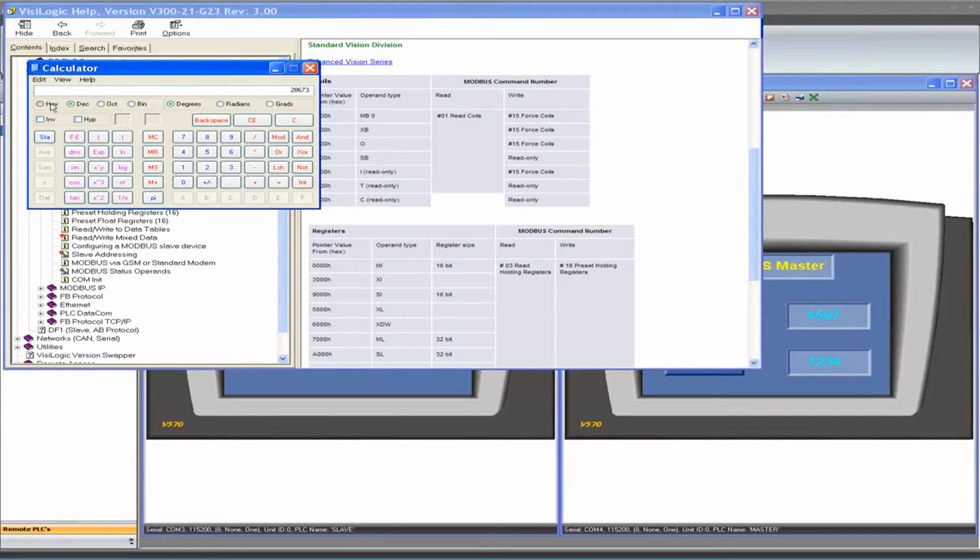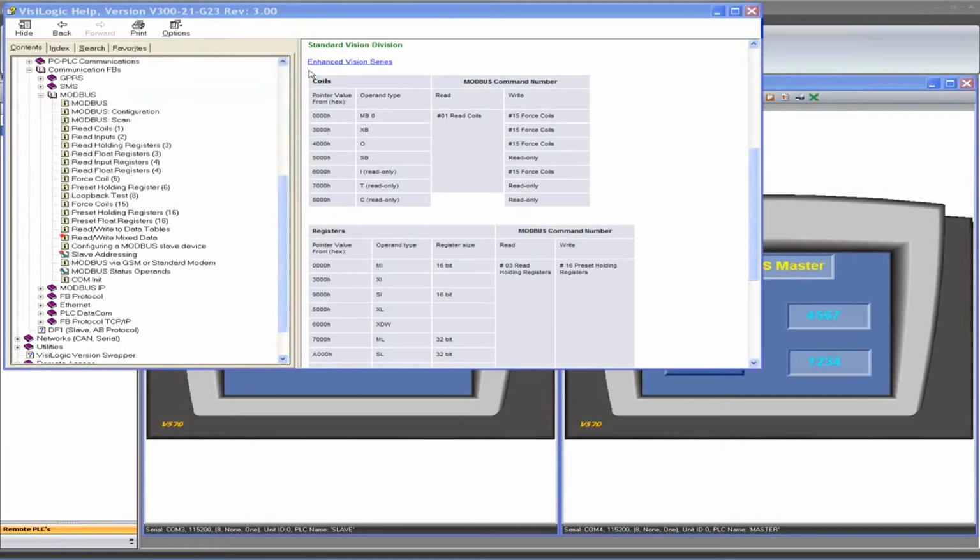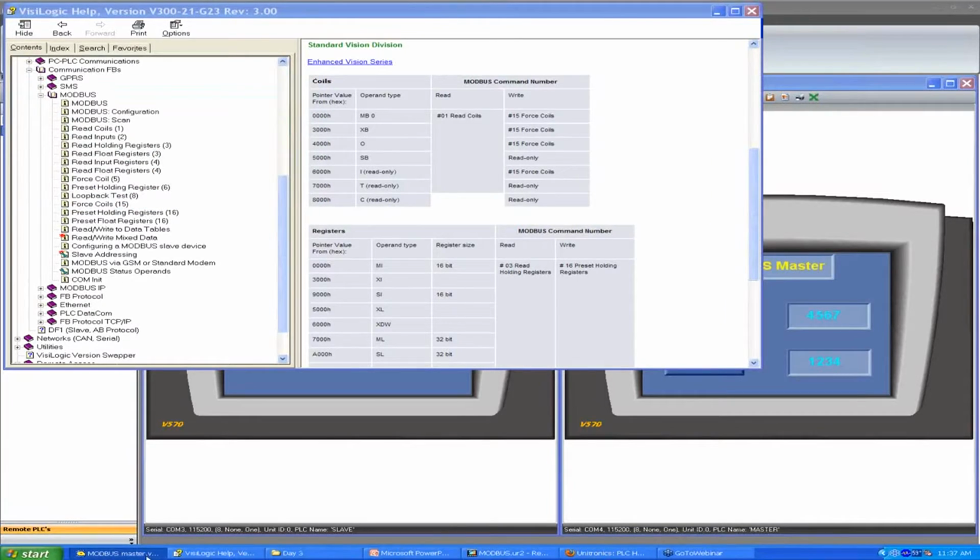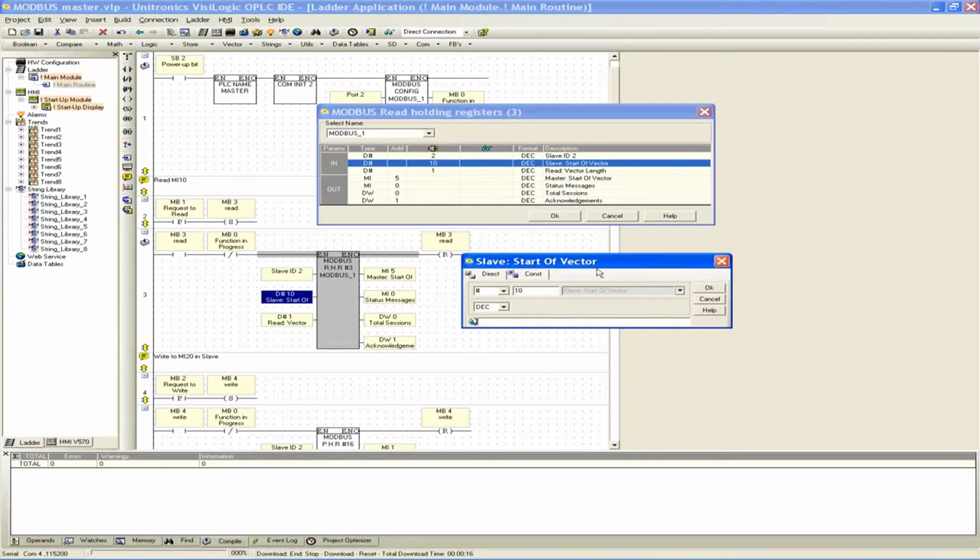you can just keep doing any of these really. I won't go through it again. But that's how you make sure you calculate your hex value, which is what we had entered back in our read holding register. So you do have the option of dropping down and picking a hex. You'll see it switches to A. You can enter this value in hex or also in decimal.